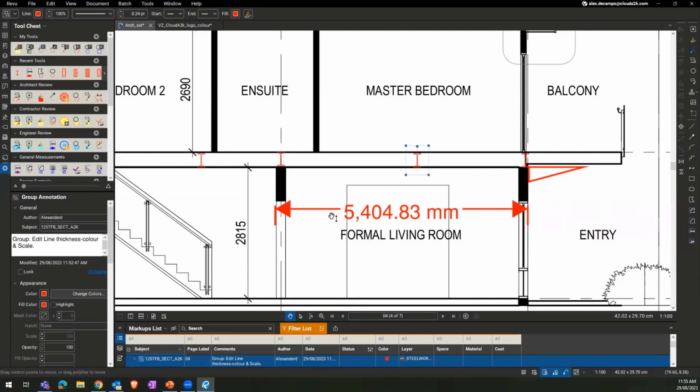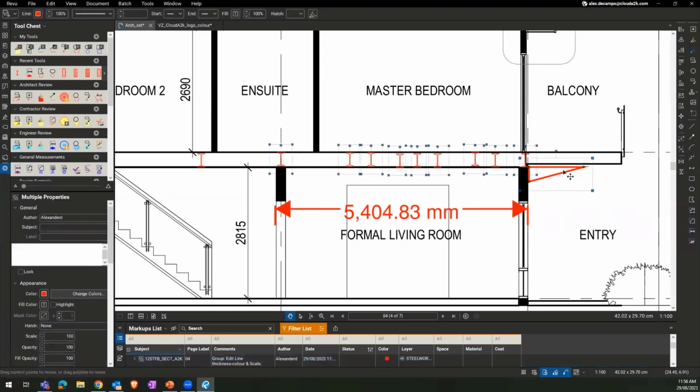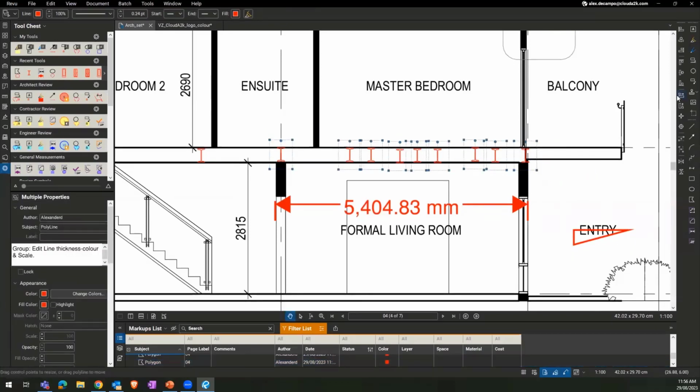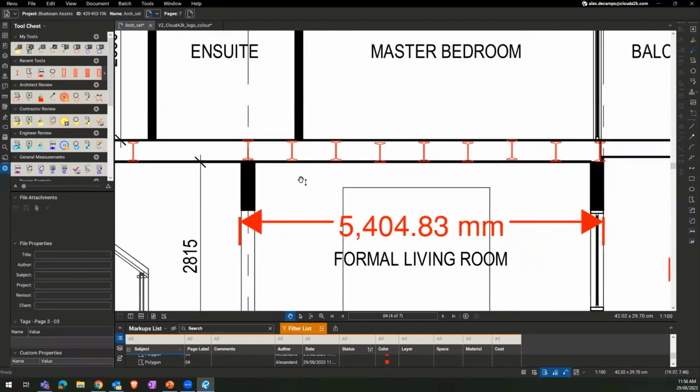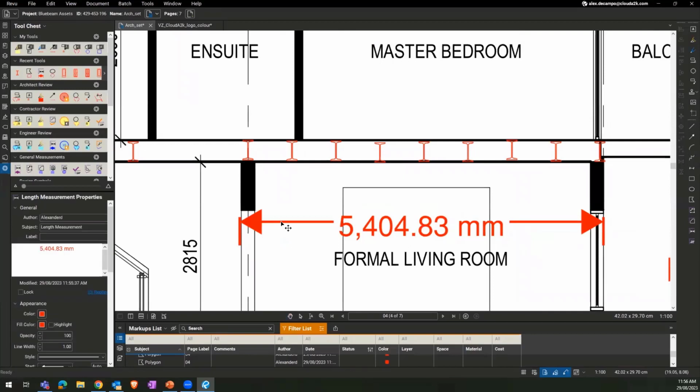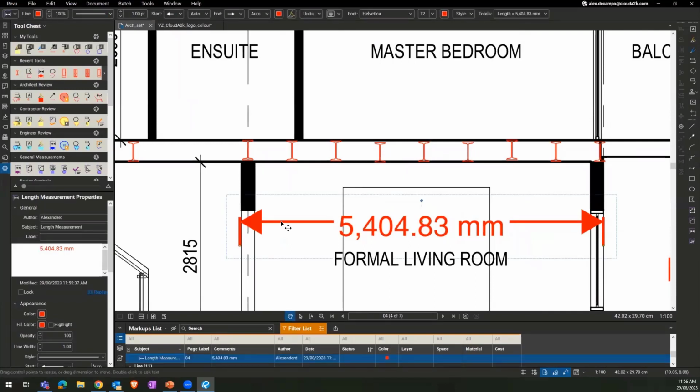So for 500 centers at 5,500 mils, you're at about 11, so you need to put 11 in. If you know how many, you can just put in the correct number and then distribute it, but you can't actually set a centers or spacing exactly. So no, it's not ideal in terms of actually doing a layout. The ideal way would be having the actual distance between each one, because you know what that value is supposed to be. But the best way to work around that in Bluebeam is to find that max distance and then do it in reverse order.